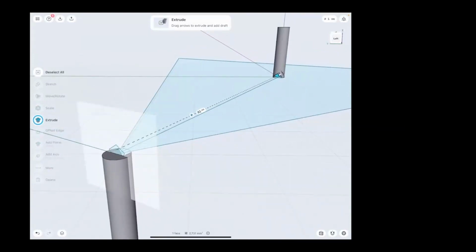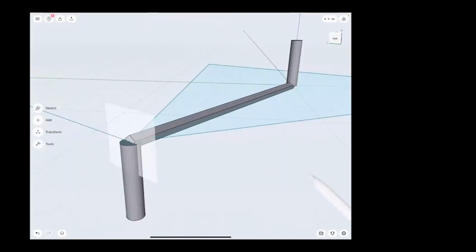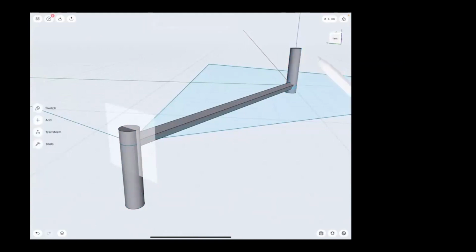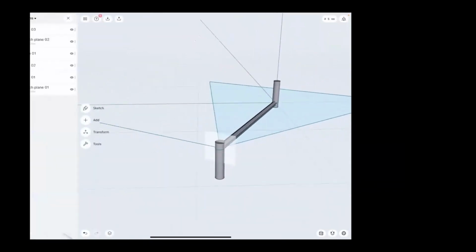In this case, we can change it anytime by tapping on that blue icon and telling it to create a new body. There are two small problems with these models, which I can solve easily by selecting the picker end and moving it upwards by 3 mm, and selecting the inlet end and moving it downwards by 3 mm. There I have the solid bodies that I can work on in the following.